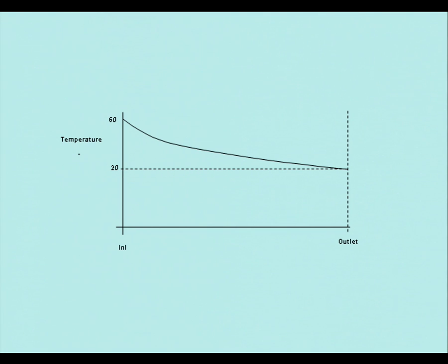I can use two things. I can work out what it is using an exponential decay halfway along, or I can take the temperature here being a straight line. So in the middle, the temperature is T1, T in plus T out over 2. And what you find is that if you do that, you'll end up with